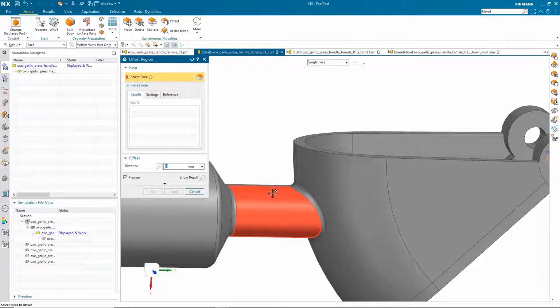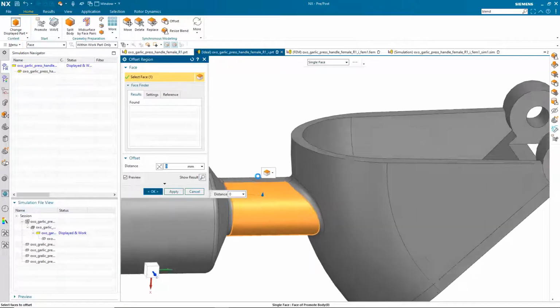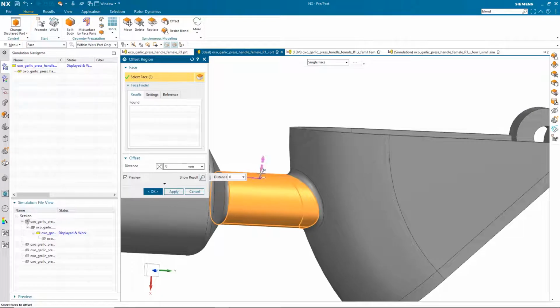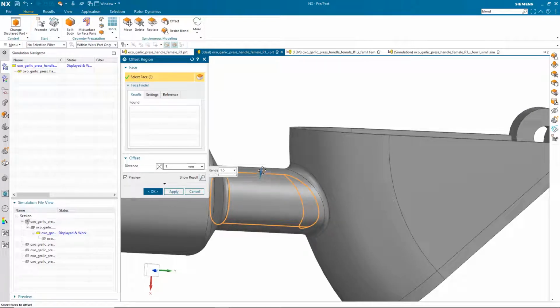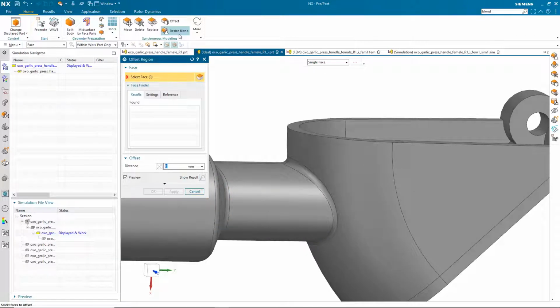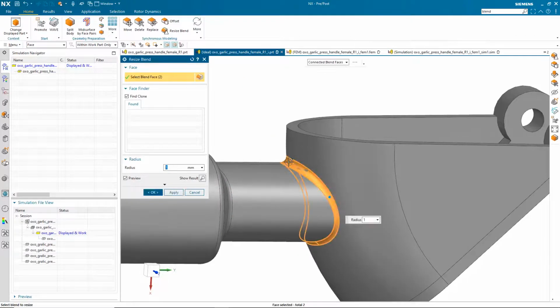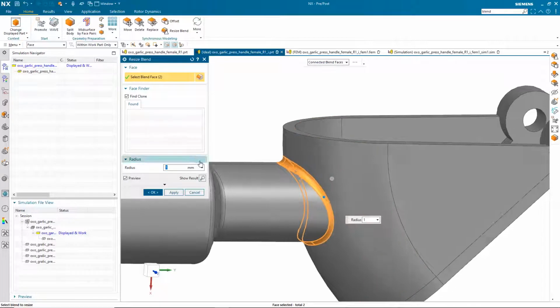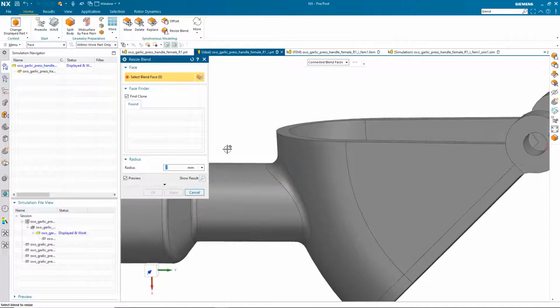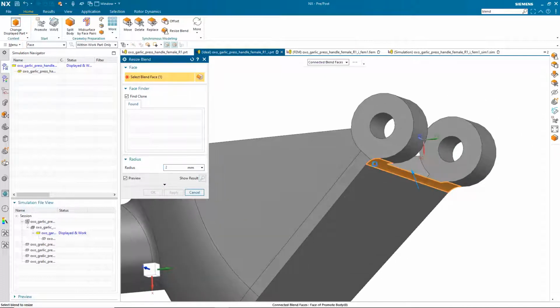So to improve the neck, what might we do? Maybe we would say, let's take the size of this and just make it a little bit bigger. How about 2 millimeters? That looks good. And what about this radius? It's at 1, but what if we doubled it? Let's take that to 2. And up at the top, that's 2.5. I'm just going to key in 3.5.